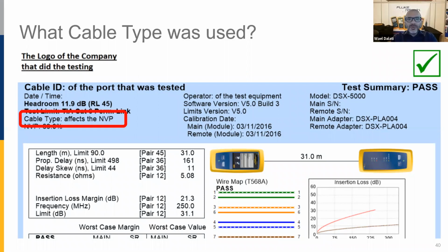I mean, it's very common practice in the field. Can you enlighten that, Salah? Yeah, so there are two ways to do that. The first is always to ask for the test report in an original Fluke format, which we call FLW. In the Fluke original format, you cannot modify the calibration date, you cannot modify the test results, you cannot modify anything. It will just be the actual measure.